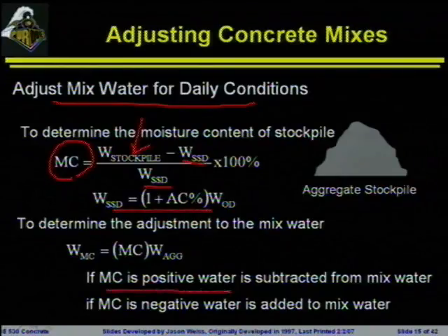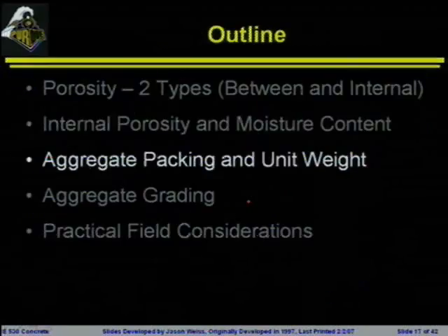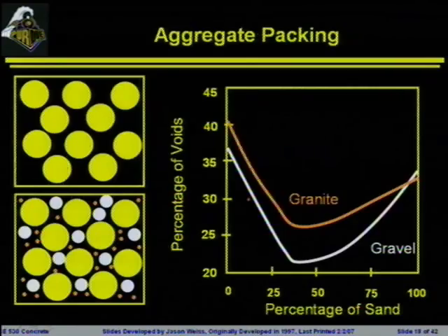If the moisture content is positive, then water is subtracted from the mixed water. If it's negative, water is going to be added to the mixed water. We will come back to this later on when we do mixture proportioning and water adjustments to make sure that we get that right. I'm going to jump in quickly into some issues of aggregate packing.